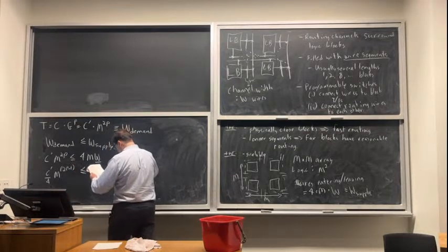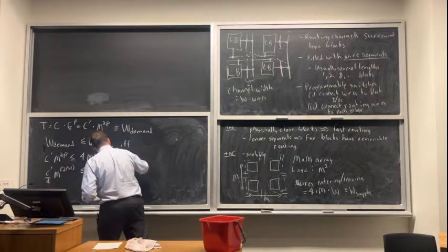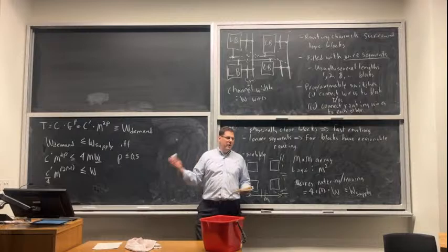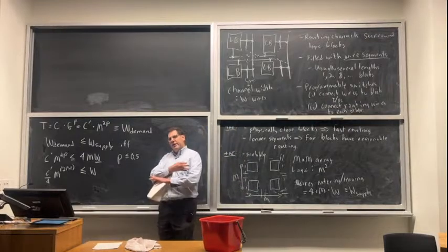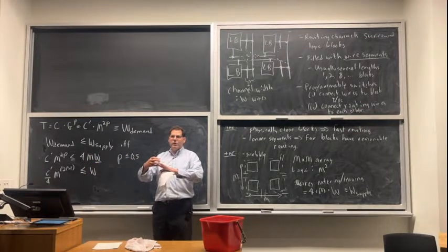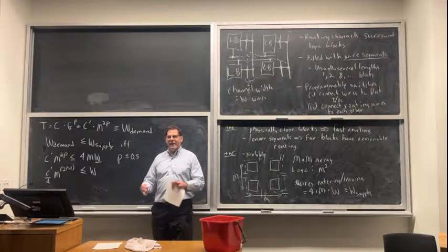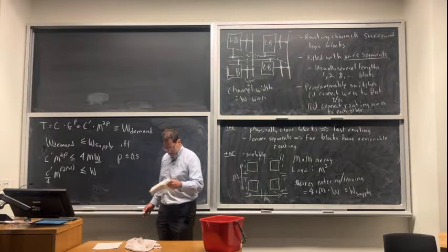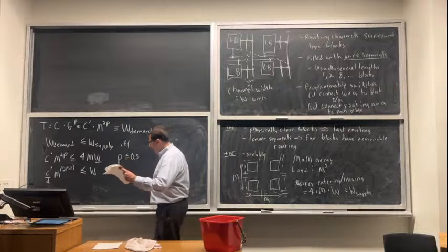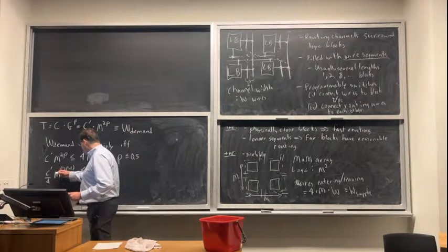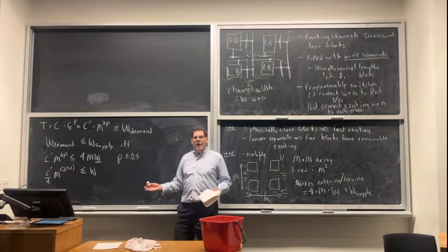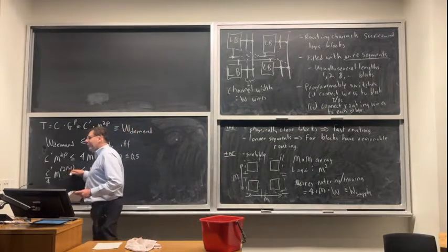We said the rent exponent is always between 0 and 1. And we said a rent exponent of 0 corresponds to a linear pipeline, really fantastic locality. A rent exponent of 0.4 corresponds to a circuit that can be laid out as a 2D array, like an SRAM or some kind of two-dimensional systolic array, which is pretty good locality as well. So if my rent exponent is 0.5 or lower, this 2p minus 1 is actually 0 or even negative. Negative doesn't really make that much sense, but basically 0 is good enough, right?